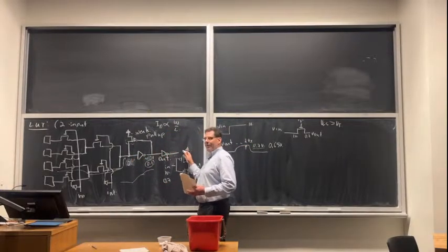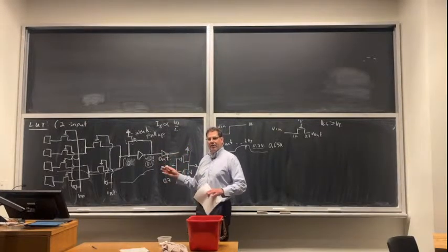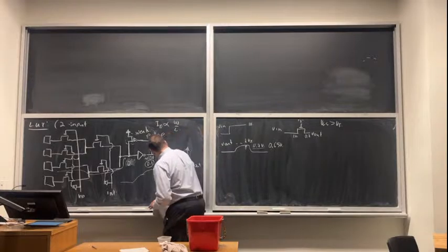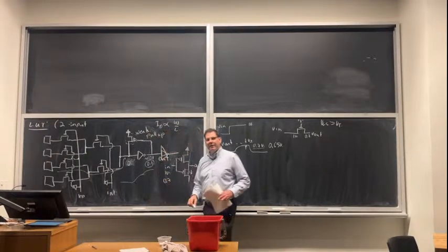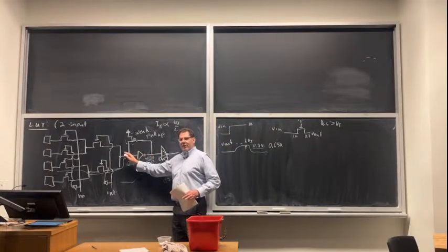But you're often driving, say, some local interconnect. That local interconnect has a fair amount of capacitance. So you actually make a second inverter that's relatively big, and that now can drive that. So this is a standard technique in full custom design as well.